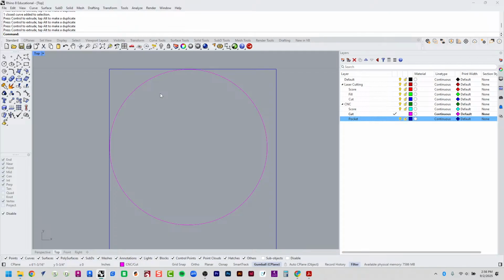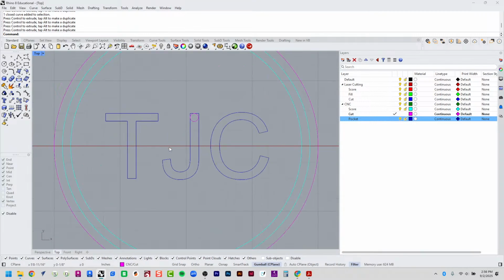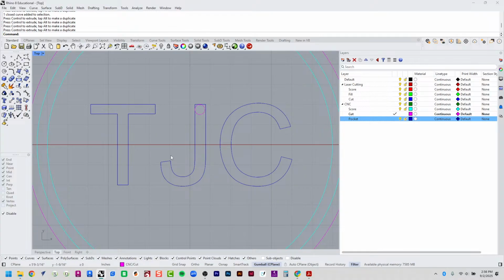Therefore, it can't chop things into 90-degree corners, especially inside corners. Outside corners, it can do with enough space, with enough room. But for something like this, creating a pocket, which is a subtraction of material within this region, it's going to have trouble creating sharp 90-degree angles.